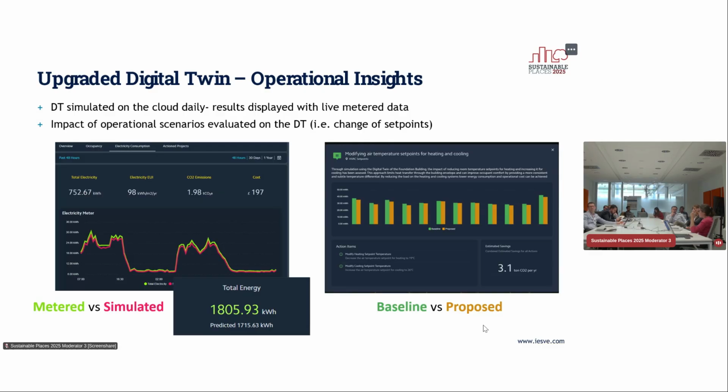Basically, the use of these charts is to identify if there's performance drift. So is there some new issue that was not detected before in the initial phase, where you're looking at the performance gap and the model was very close to the building? If those two start to drift, like the model runs with the same weather data that's in the real world, then something is happening in the building that's not accounted for in the model.